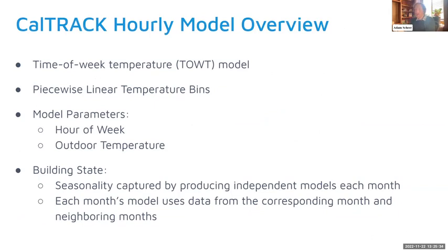Okay, now the hourly model. I'm not going to dive super deep on the hourly model. There's much more that goes on in the hourly model. For those of you who are familiar with the terminology, it's a time of week and temperature model, meaning that the model parameters or the variables are the hour of week and the outdoor temperature. It's a piecewise linear model, so there are a number of temperature bins for which data are fit independently. And in addition to those aspects of the model, there's also an occupancy parameter, and there's this building state.